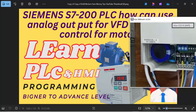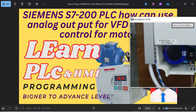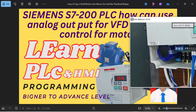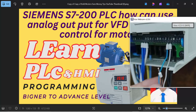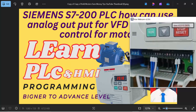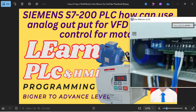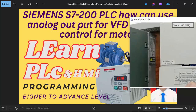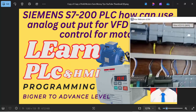As you can see, this is my reverse forward command. And this is our analog output command. You can see this one, the analog output command, and this black is MPT, which we are not using. This blue wire is plus 10 volts, 0 to 10 volt, and this white one is for minus. This we will use in our program, so let's get started.